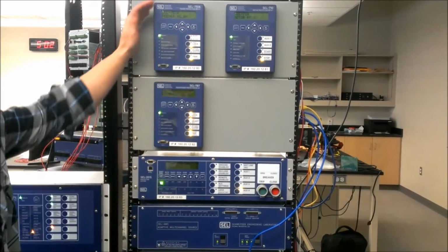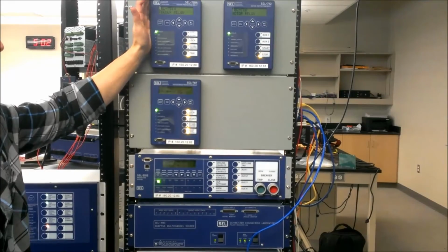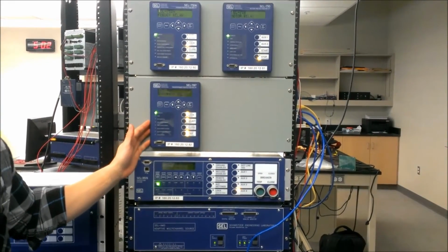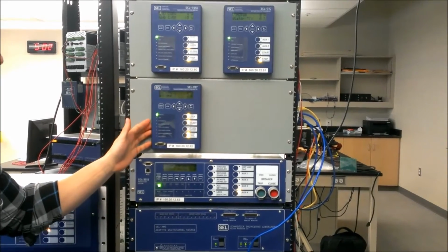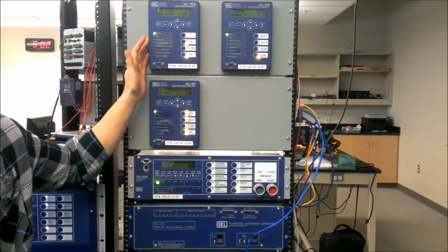We have set up our GOOSE messaging using the SEL Architect program. To confirm that the GOOSE messaging is being sent across the network, we have set up a simple handshaking sequence. To start with the sequence, when the 751 receives that overcurrent value, it will publish a message to the 787. When the 787 receives that the 751 has tripped, the 787 will then send a message back to the 751 that it has received the bit.